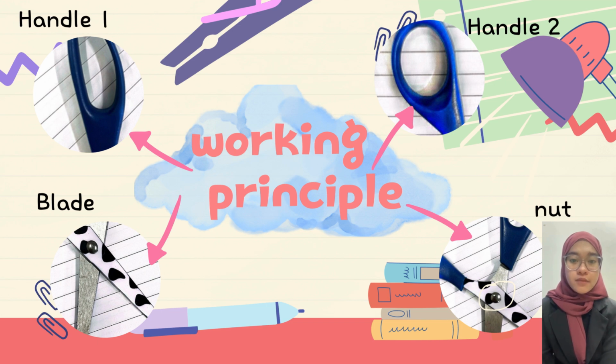The working principle of scissors is based on a simple lever mechanism. The pivot rivet acts as the fulcrum, while the handles act as the effort arm and the blade acts as the load arm. When force is applied to the handles, the blades rotate around the pivot and create a cutting action.